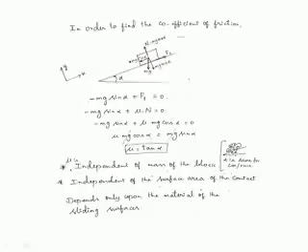I'll tell you an example. It means that it does not depend upon the mass. On an inclined plane, if there is a car and a bike, and we increase the angle alpha of the road, both the bike and the car will start to slide at the same angle. That is the beauty. It does not depend upon the mass of the block, it does not depend upon the surface area of contact, and it depends only upon the nature of the material.